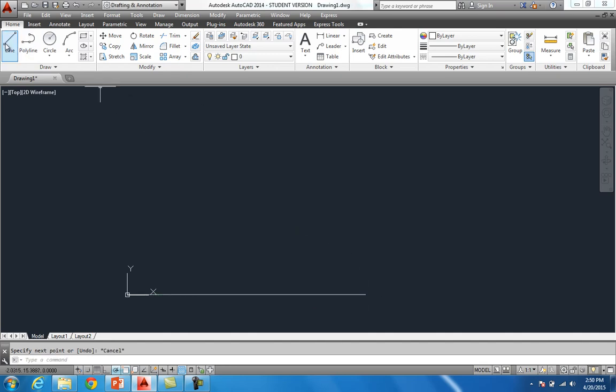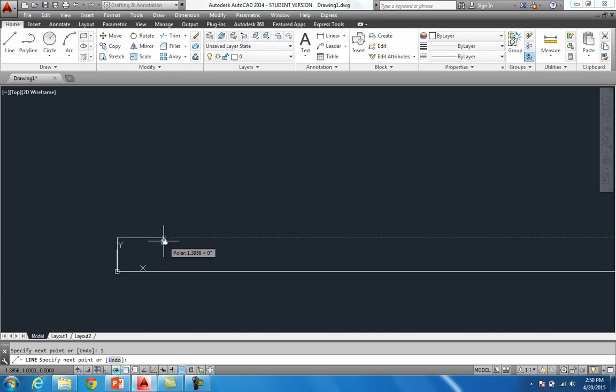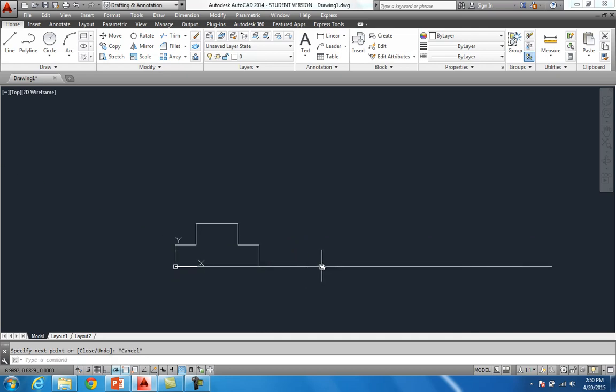When you're doing the cavalier or cabinet, you've got to remember one thing: you draw up the front just normally. If you have something that you're looking at straight on, let's say this comes up 1 inch, this comes over 1 inch, and then you come up 1 inch, then over 2. I'm just throwing this up here, then 1 inch over, and then straight down. You would draw the front just normally on both oblique types of drawings.